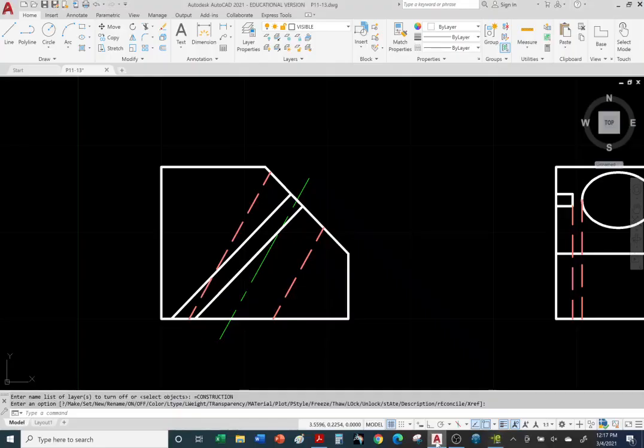And we should already have that. Yep. We already have the red hidden lines for the hole and the green center line for its axis. Notice how they're not at the same angle. Typically you wouldn't machine a part like this, but the author decided to make this a little bit more challenging. So she's forcing us to create 2 auxiliary views, one looking down the rectangular groove and the other one looking down the axis of the center line, or the circular hole, I should say. All right, so that's complete.